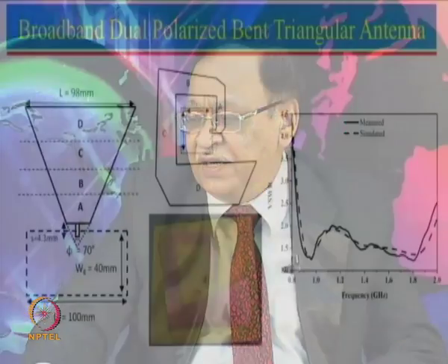But now we have actually noticed that the polarization does not remain vertical all the time, especially after multiple reflections, the pattern changes, and also if this is mounted over here, there will be components which are horizontal as well as vertical. So we needed an antenna which should receive both horizontal as well as vertical components, not just the vertical component only. So we were looking into a configuration which should give us broadband as well as multiple polarization. So let us just look at an example here.